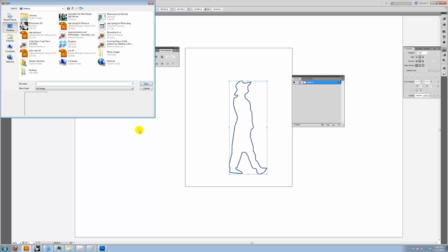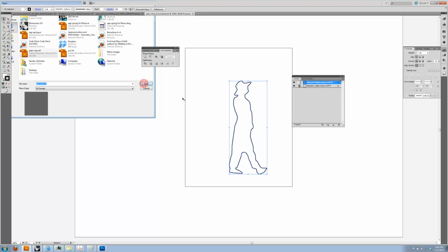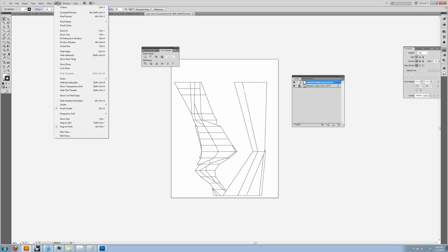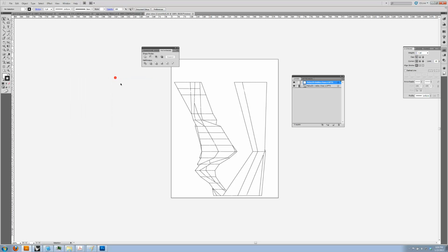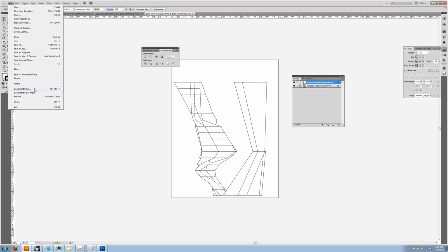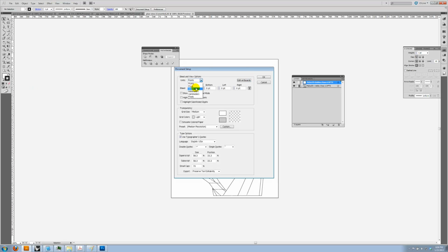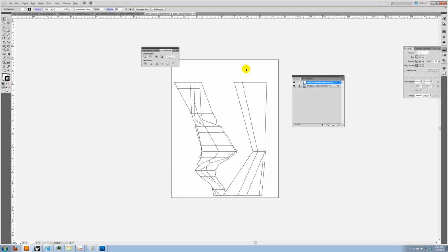If I go into Illustrator, I can open up that file that I just made, plan view, and I'm going to get my drawing. If I look at the rulers in the drawing, I need to change my units. Units are inches. So we can see that this thing is roughly 4.5 feet across, and this other one is roughly 3.5 feet. So that's right human scale for that drawing. We're in good shape here. I've got 2 layers for this one. I have this Make2D, Hidden Lines, Lofts. I'm going to go ahead and change that to Plan, Hidden.